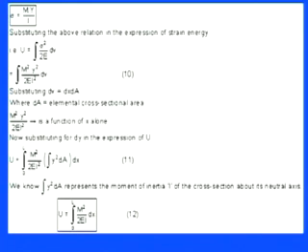So we have the strain energy U, which for the entire beam is the integration of sigma square by 2E into dV. Now we know that sigma is nothing but M into y divided by I, so we need to replace that part. So we have the integration for the entire domain of the volume, integral of M square y square divided by 2E into I square into dV. We need to substitute the volume in that particular domain, so we have dx, because the variation is there in x only, because sigma x is in the axial form, into dA.